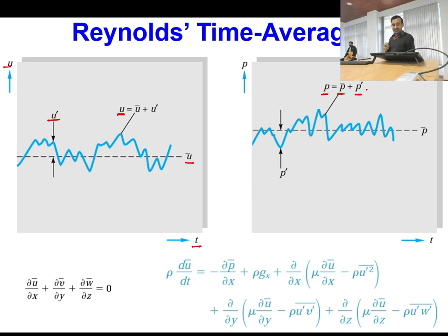Now, the second important point is that the major issue in turbulent flow is the determination of the fluctuating components, because they are very chaotic. There is no specific arrangement or trend which can mimic these fluctuations. So if we consider the fluctuating components in our analysis, or the actual velocity u or actual pressure p which includes them, it becomes very challenging. That's why we define some time-averaged mean parameters and solve our governing equations for these mean parameters. Along with these, if any fluctuations are to be accounted for, we develop semi-empirical theories so that we can approximate them in terms of the mean parameters. That is the whole idea of turbulence.